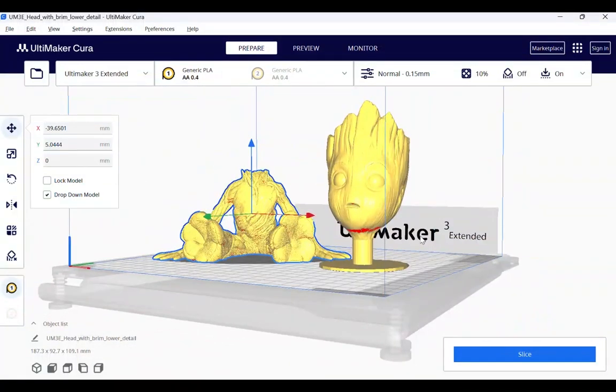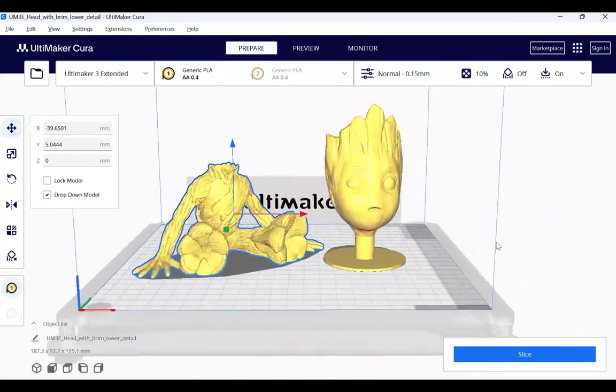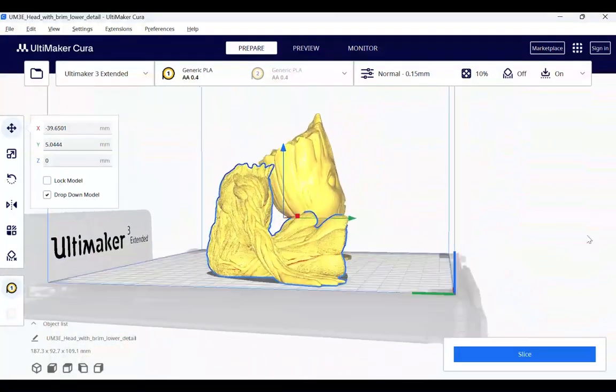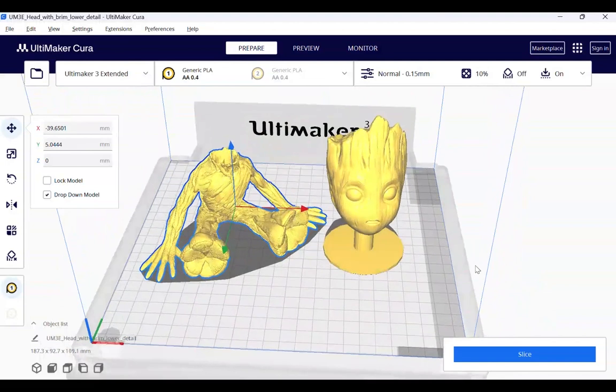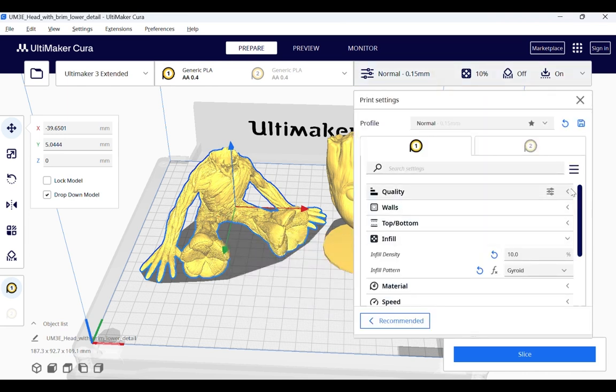You can see there are some spots where the slicer wants to add support material. Once again, I'm going to go based on what the modeler said and avoid using supports. However, we will still go over all of the settings, make sure they are exactly as we want them to be. Make sure we aren't holding over anything from our last model that we don't want to use those settings.